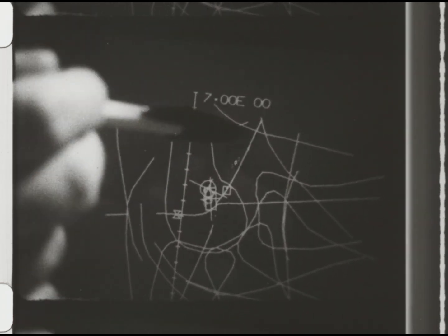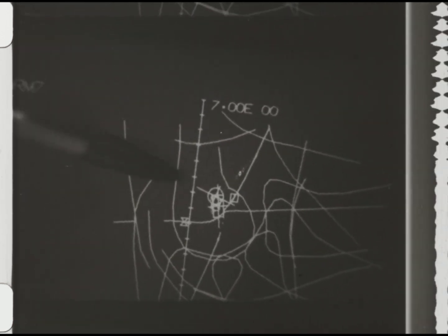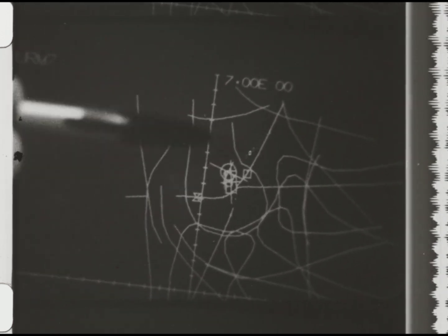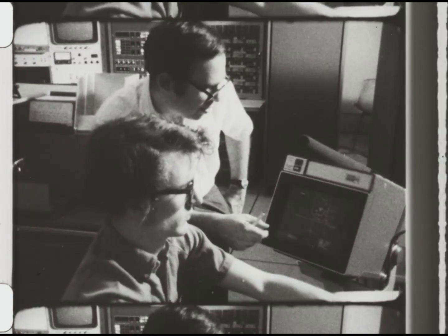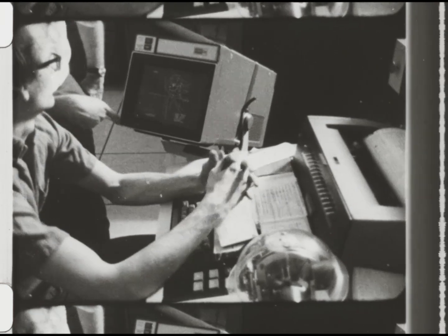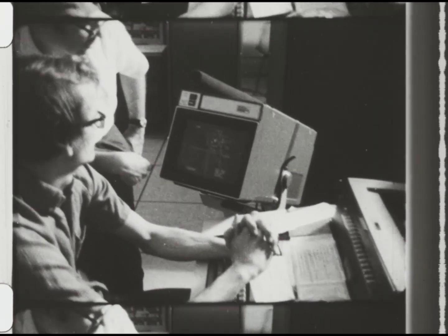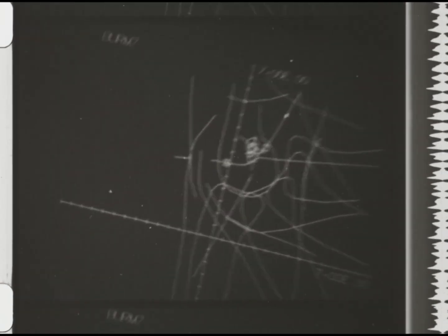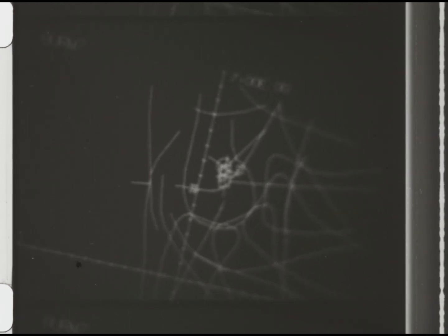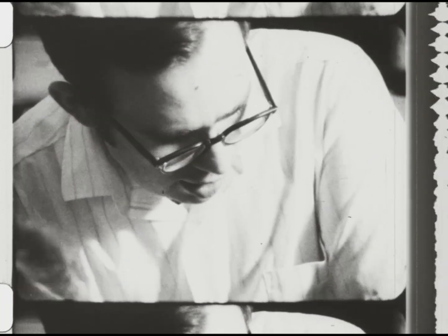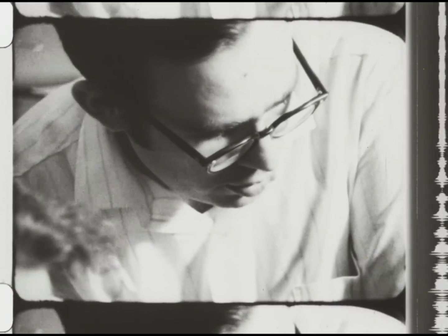And that really represents a possible link for a mechanism which would be capable of guiding the leg through these desired design positions. He just selected that as a possible link for the mechanism. The computer is now typing out on the console exactly the coordinates of the particular circle point, center point pair that he just selected. This bouncing spot up here represents a possible crank for a linkage that will guide these bodies through these various design positions.